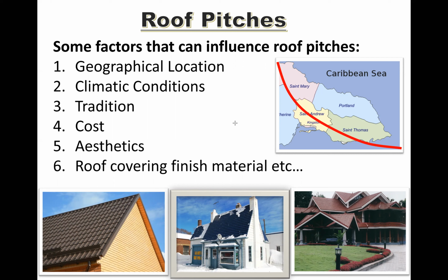Nowadays we have churches with all kinds of roofs, but that's just a tradition. So it's a factor that one could consider. Cost is also a factor. We know that on a pitched roof, the maintenance is going to be higher than on a flat roof. So over time you'll have to do some repairs and stuff like that. A person might say, I don't want to spend so much money on that roof. Even in the initial construction, you can have a higher cost, but the maintenance certainly will be higher.